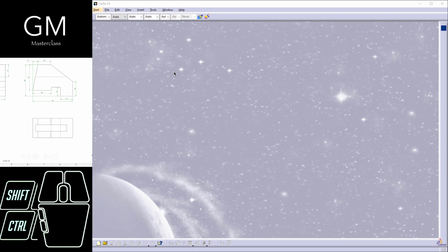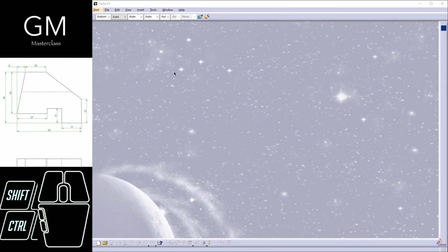If I were the person who is going to manufacture this model and I do not find information about the unit system, then I can assume that these are millimeters. Even if I have a value like this that probably refers more to inches, the mistake would be on the person who did this engineering draw.